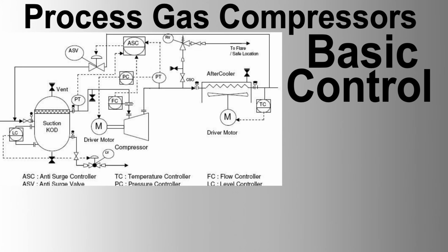C. Suction and discharge pressure management. Centralized control ensures uniform suction pressure across all compressors. Implementing shared control loops requires precise tuning to avoid conflicts and ensure stability. Adjust control valves and VFDs based on combined feedback from all suction and discharge pressure transmitters.